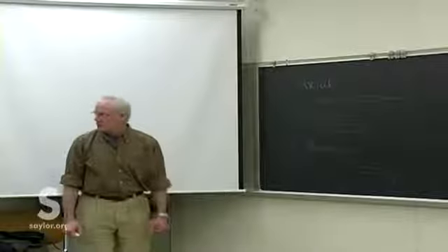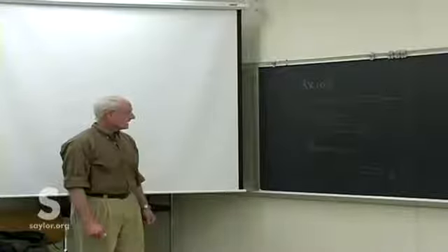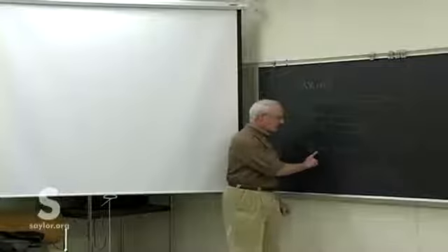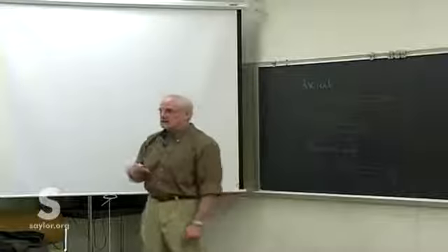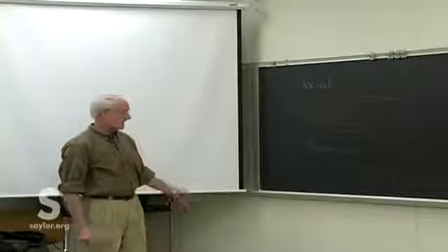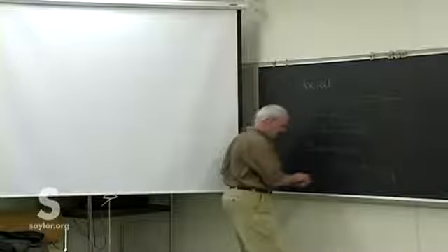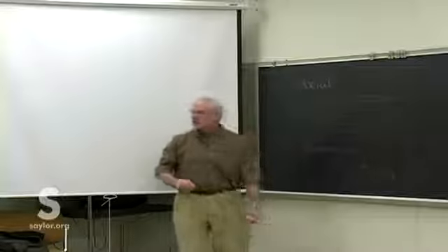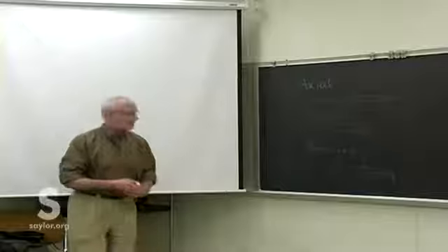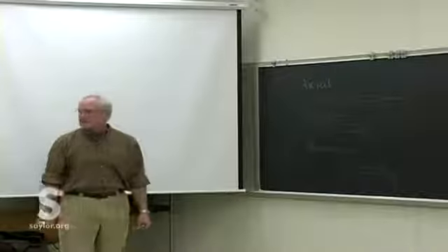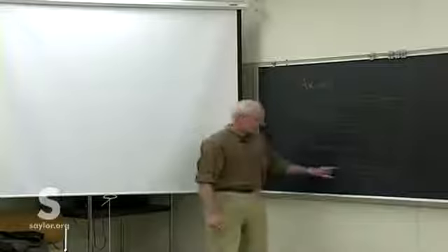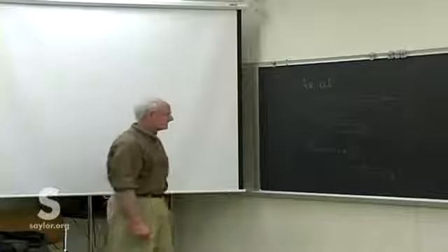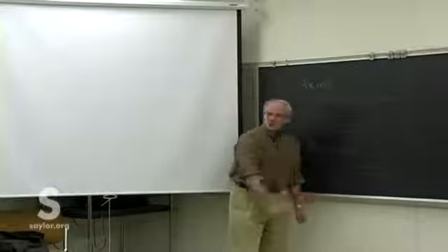What we're going to review again then this morning is the shear and moment diagrams we get from that, because what's going to be a big concern to us now is how these beams respond to this kind of loading. It's not any great shakes to know that these are going to bend something like that, but any place you've got a curve in the beam like that, that's internal moment, and we need to look at that. We need to see, can the material withstand those kind of loads? There's also, of course, shear across here, as well as the internal moments.